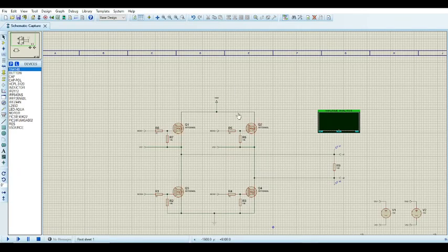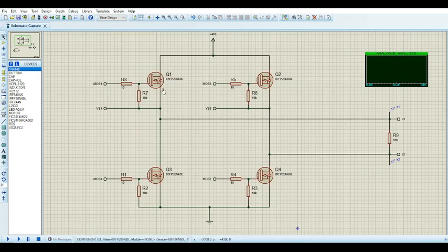First I'll just show the basic schematic of what I'm talking about. So this is a full bridge inverter with N-channel MOSFETs, driven, and you have two MOSFETs, so these two are turned on at the same time, and these two are turned on at the same time. So basically, the whole point is to have a sine wave across the load, and to vary the PWM across a MOSFET pair over half of the frequency that you desire. So looking at the code, that'll make much more sense.